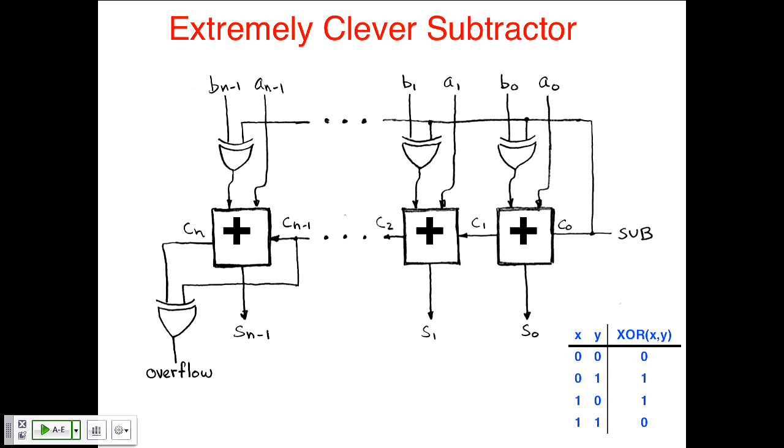So now we're starting to get the feel of what an arithmetic logic unit looks like. It's a block that can do several functions controlled by some control lines. So this is a control line that's changing the function it performs on the inputs and outputs. So this guy has two functions, add or subtract, and this is one way of building that using a bunch of gates, all right? So notice we reuse all the adder functionality. We don't have a separate subtract circuit. It's just one adder circuit plus a layer of XOR gates to change its behavior. Okay? It's a good time to ask questions.